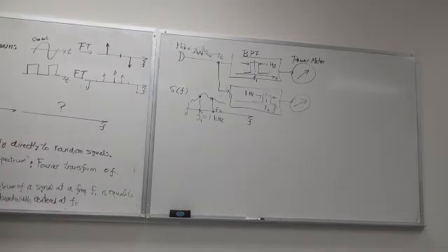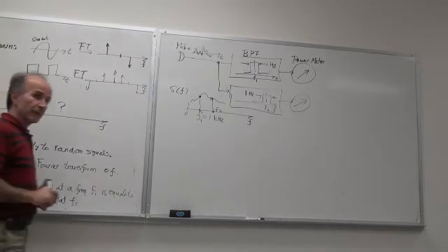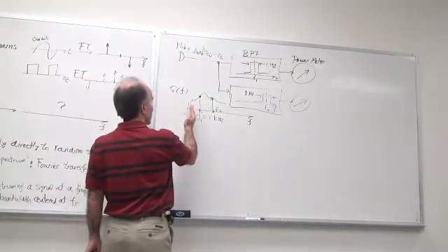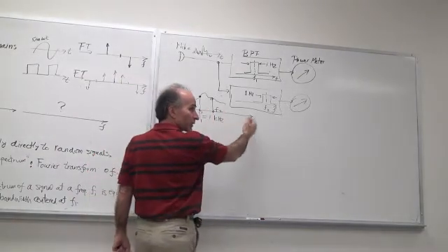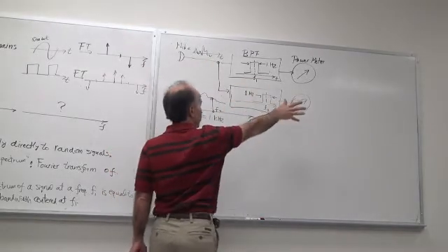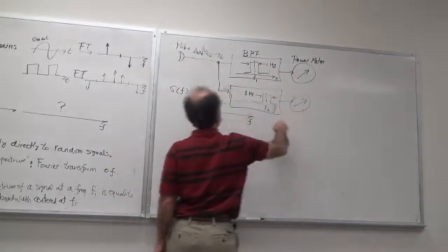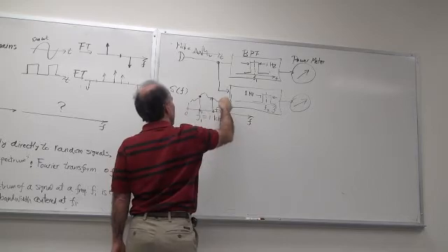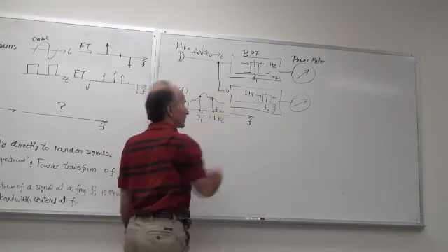So in principle, you have a whole bunch of bandpass filters centered at 20 hertz, 30 hertz, 40 hertz, 100 hertz, 1 kilohertz, 2 kilohertz, etc. Right? And your signal is driving all of these bandpass filters, and you're measuring the output powers of all of these, and you're finding these points and putting them here. And the result is what we call the spectrum.